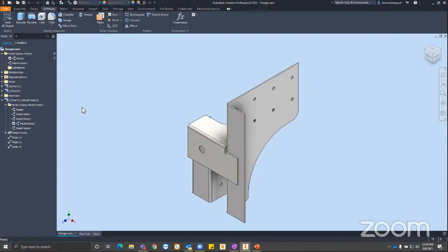So this might be, I created a design view, so when I go to place this part on a drawing, I'm only seeing this specific piece or this IPT file inside of the drawing. A lot of the time, people use level of detail to accomplish that, and unsuppressing and suppressing components is not something you want to get into the habit of. Design views really take that role.